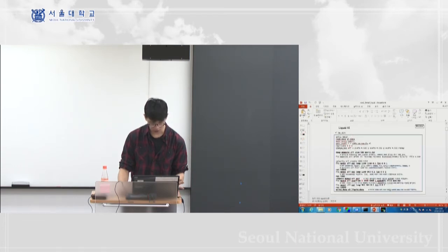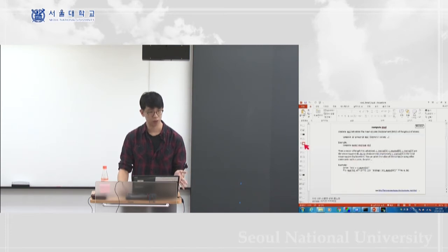Here we make a print for c_myMSD[4], and as implemented, the compute MSD gives you 4 values: the mean square displacement for the x direction, y direction, and z direction, and the last one is the total mean square displacement. Here we want this total mean square displacement, so we're gonna make it print out the 4th value of the MSD.